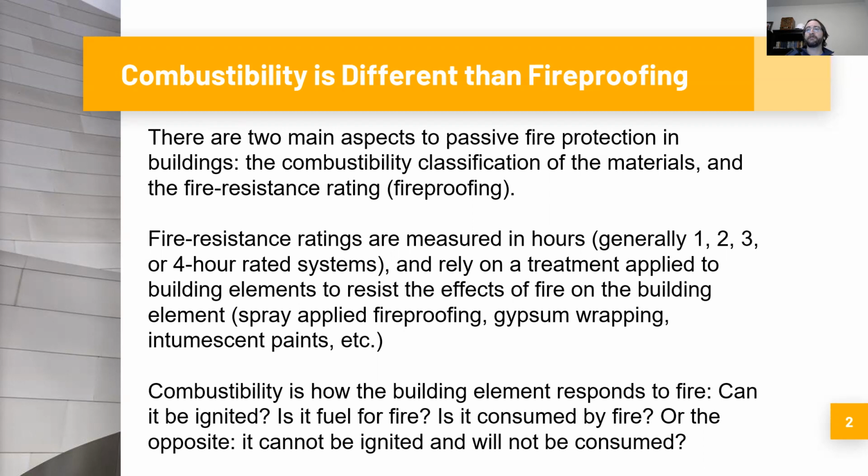And on the contrary, a non-combustible material is one that cannot be ignited and will not be consumed by the fire. Now, that's not to say it's not affected by fire, because even non-combustible materials are affected by fire, but is the material consumed by the fire? And can it sustain a fire? Is it fuel for a fire? One way you can think about this is if you apply a flame to it, will it burn? Will it catch fire and burn?